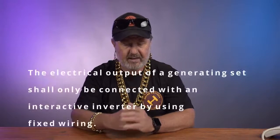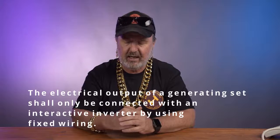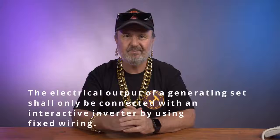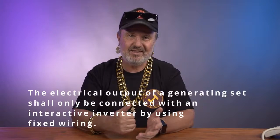So that's one of the reasons why in AS/NZS 4509 Part 1, we specify that the electrical output of a generating set shall only be connected with an interactive inverter using fixed wiring, permanent fixed wiring, to a dedicated circuit breaker. So it's not a plug, it's not a socket inlet with an extension cord plugged into a generator.